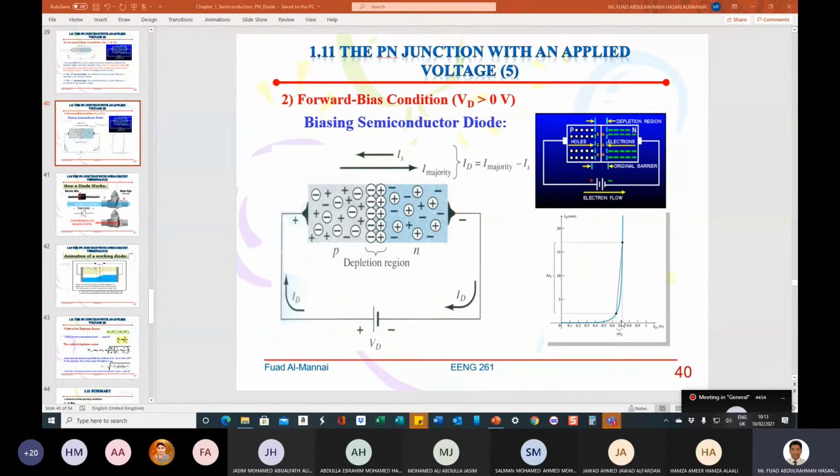If you put 5 volts, it will be on. But if you put a battery that is 0.3 volt, the diode will be off, because you didn't put sufficient voltage across it to overcome the built-in voltage, or sometimes we call it the threshold voltage.